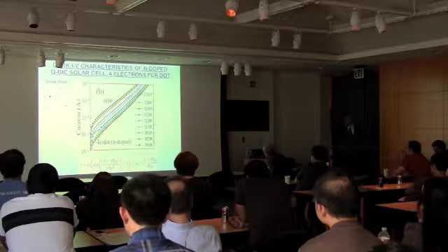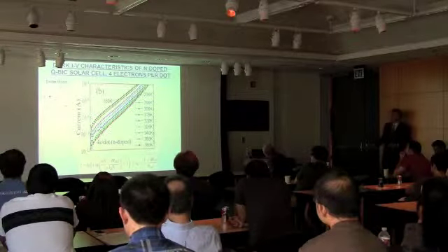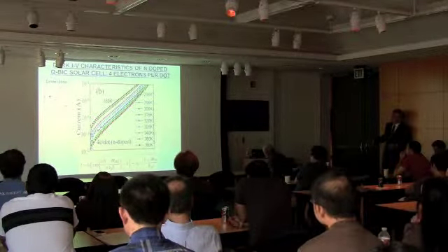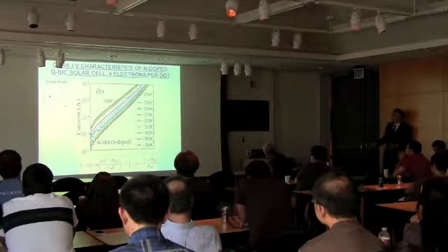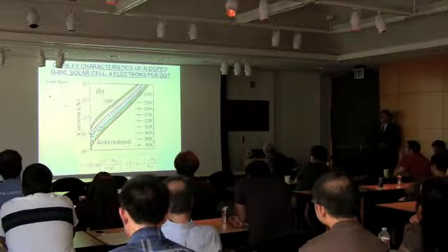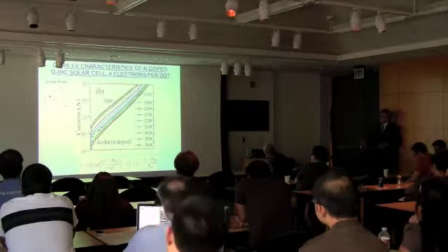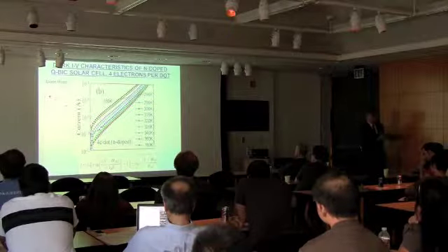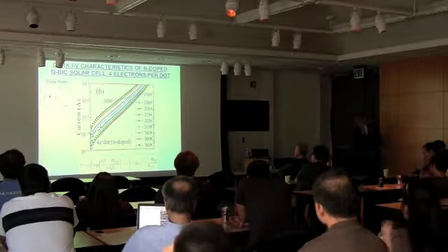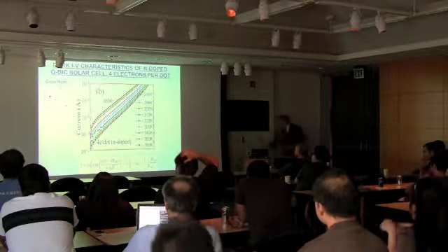You see that current increases, here in a semi-log plot, practically exponentially. So using measurements at different temperatures, we determine these parameters of the diode. You don't even need to do solar cell measurements to see the quality of your material, yeah? How good a p-n junction you have.